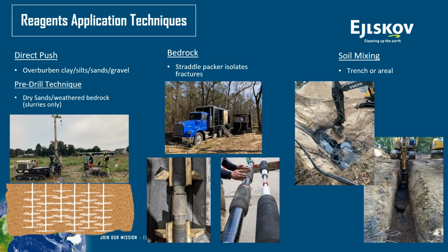And again, as I just mentioned, you can apply slurries or liquids into sands and gravels, but when it comes to clays and silts, that's really where slurries have an advantage over liquids. Okay, and that's usually done. Most of our projects are done using direct push.